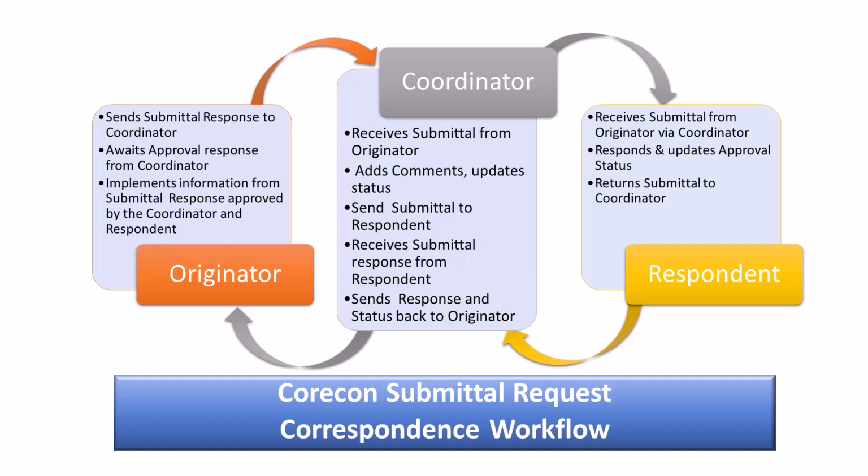In the case of a general contractor, submittals are requested first from the subcontractors and suppliers per the project specifications. They are then submitted to the respondent for review and approval. On occasion, items that are rejected in some capacity will need to be resubmitted, which may warrant creating another submittal. Upon final approval, the general contractor will return the approved submittal and related documentation back to the suppliers and subcontractors so materials can be purchased.